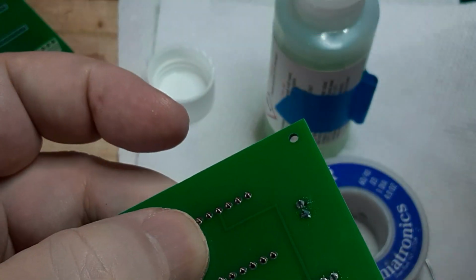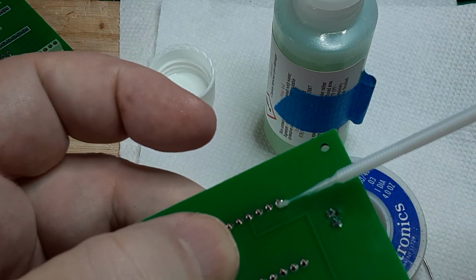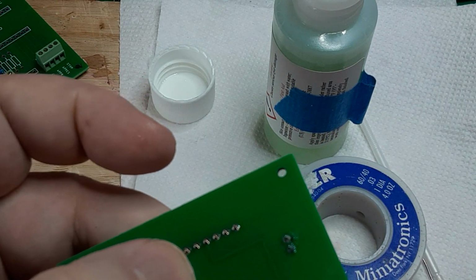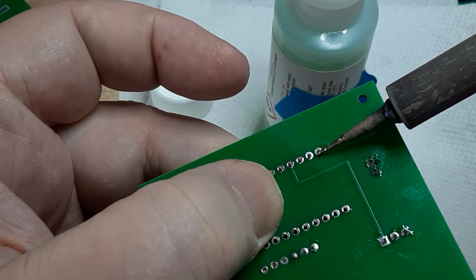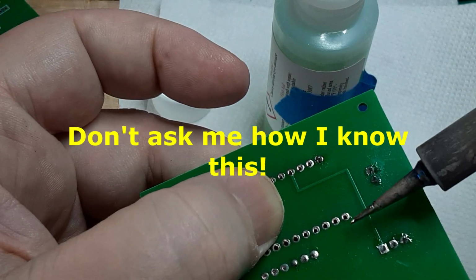Now solder the header block pins to the circuit board. You might be tempted to solder just those pins that require an electrical connection. Resist that temptation. The solder joints provide mechanical strength as well as electrical connectivity. If you do not solder all the pins, the header block might pull loose from the circuit board when you try to remove the Nano.